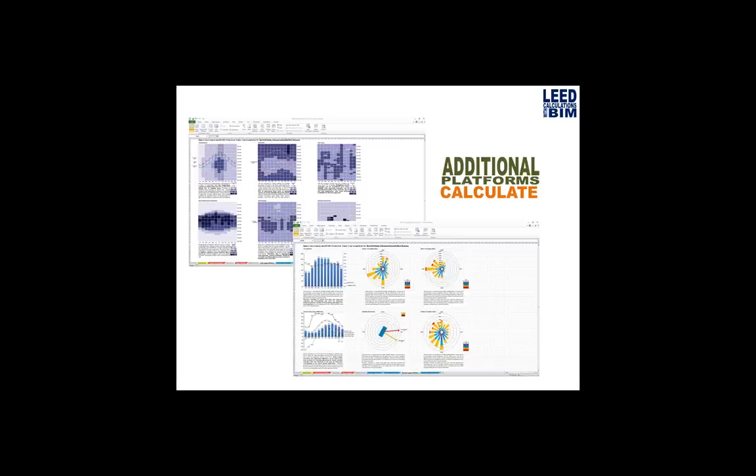And you can get this information from Ecotect and Climate Consultant, but we do this for really two reasons. One, we want to be able to tailor what these graphs look like, right? So we can actually overlay information on top of each other, and we can designate what we want to see. And the other reason that we do this is that we have access to the back end in a sense. So if some of the output doesn't make sense to us, we can actually go back and look at the raw weather file, and we can look at our pivot charts to see what the input data looks like, to really understand better what the output is. With Climate Consultant or with Ecotect, you really don't have access to any of that information. You just pretty much have to take their word for it.